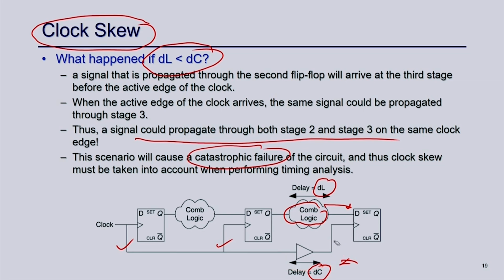Suppose whatever the clock is coming here. So, suppose I am talking about clock 2, right. So, clock 2. Usually what will happen in clock 2 is, whatever the data is here, that will come here, and whatever the data of this register is, that will go out, right, in clock 2. In clock 3, whatever the data of this is, it will come out here, and whatever the data of this that was fed in clock 2, that will come out of this register now, right.